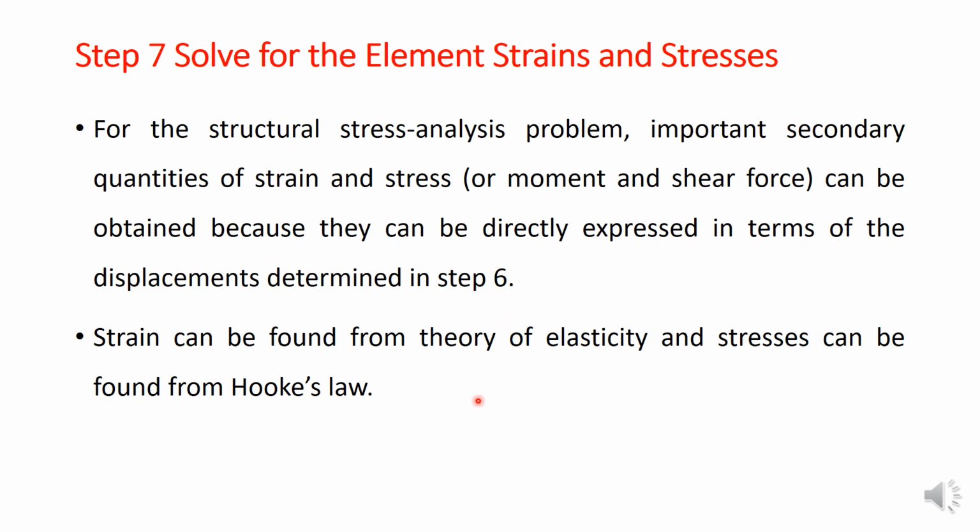We can also find the stress in the x direction by using Hooke's law for the one dimensional case, which is sigma x equals E into epsilon x. So from there, we can find the stresses as well. That is what we do in this particular step. We find elemental strains and stresses from the equations that we already defined in step 3 of FEM.